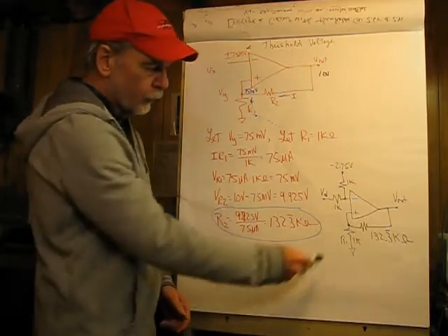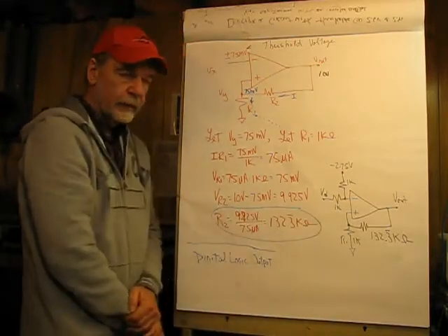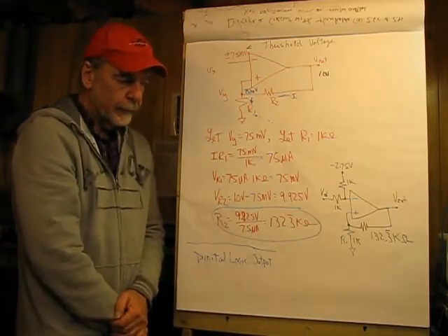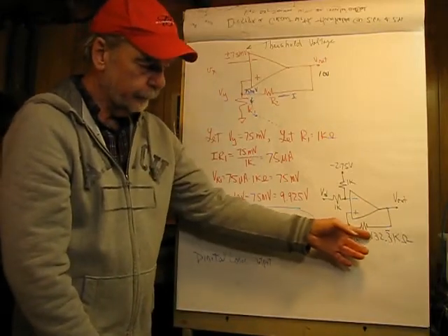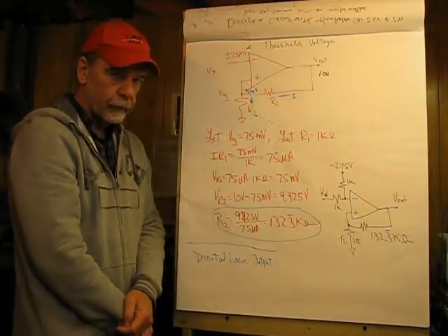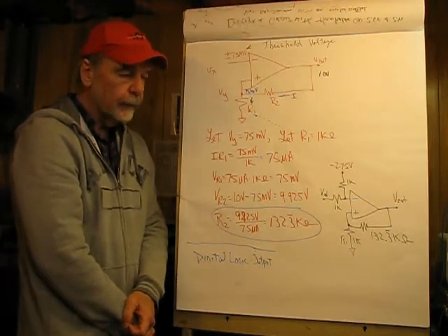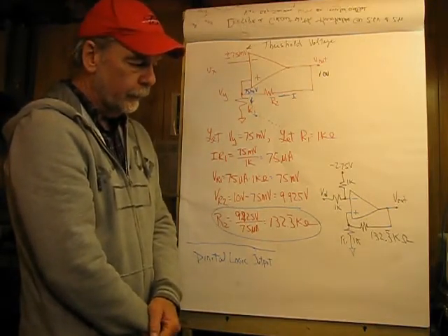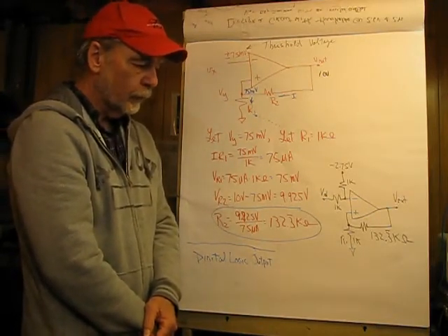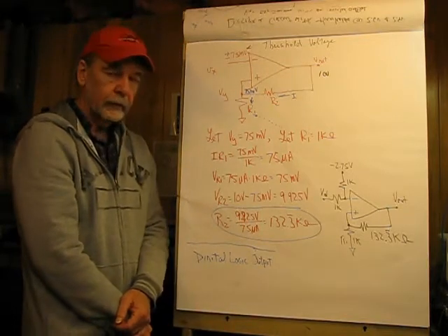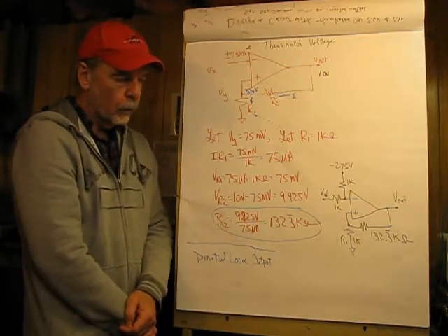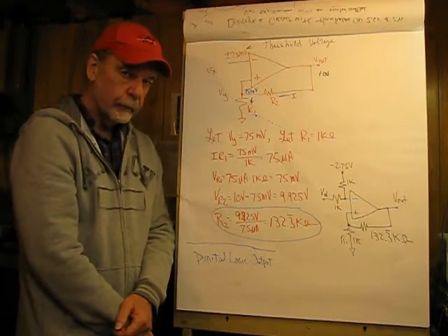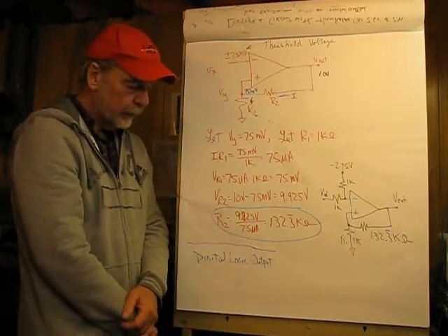So this is what the circuit would look like, which would actually meet the customer's requirement. Now, these values here are very precise to meet that, and realistically you'd be probably looking at 1% resistors and settling for close, or putting an adjustable in, making it precise.